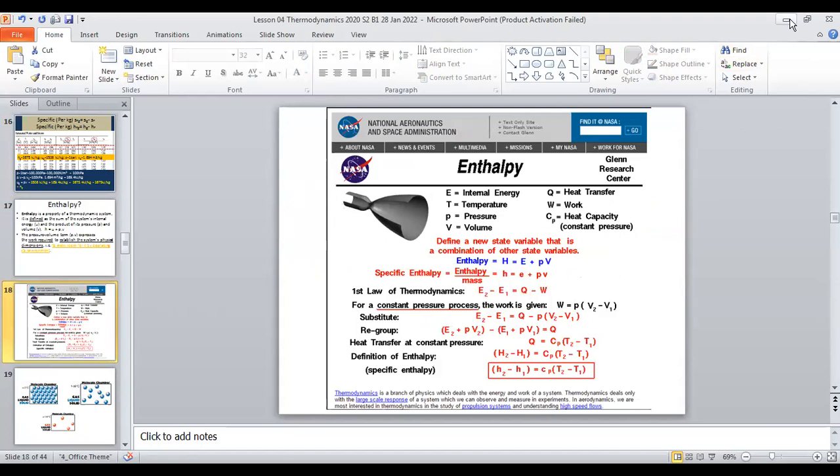So H is internal energy plus the work necessary to flow in and flow out. So H is U plus PV. You have an upfront understanding of this. That is very important. If you have no upfront understanding of H, you have issues imagining this. The flow comes in, moves out. To move out, you have to displace whatever is upfront. Going in, you have to displace whatever is upfront. So there is a flow work. To flow in, work is needed. To flow out, work is needed.